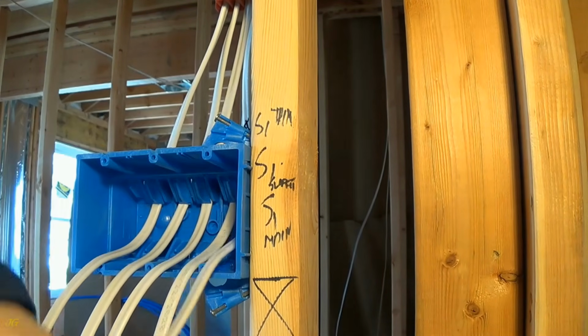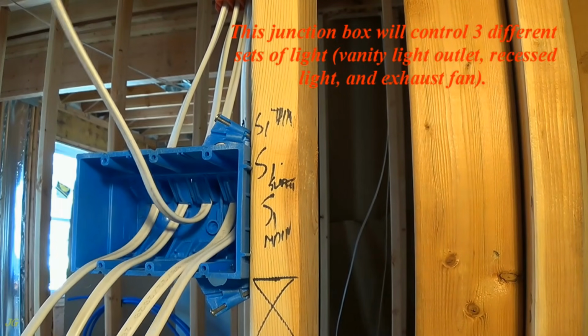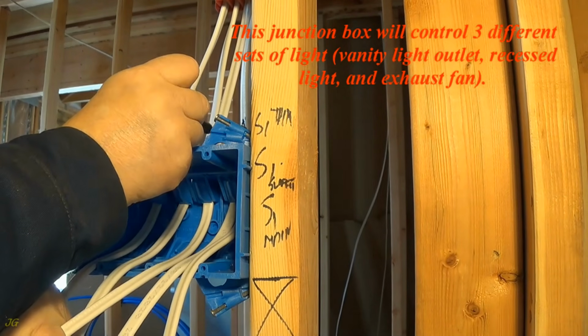Re-describe the cables. This junction box will control 3 different sets of light: vanity light outlet, recessed light, and exhaust fan.